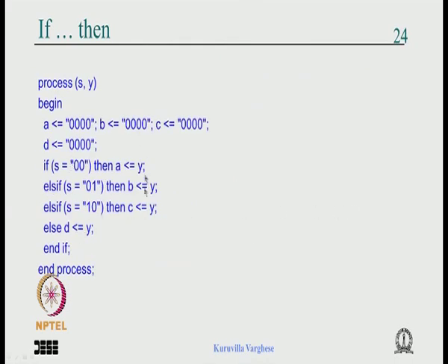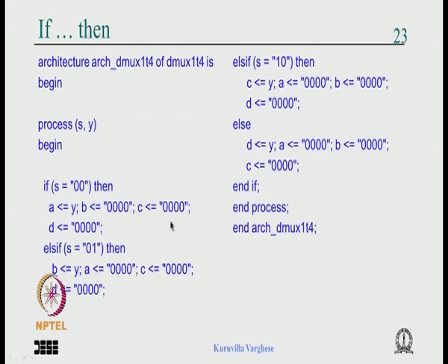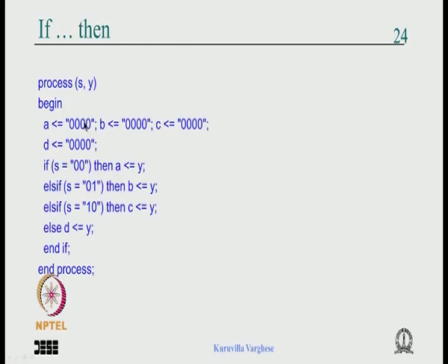Similarly, instead of repeating all the other signals here, you could initialize everything at the beginning and only write what is changing, like in the case. So these are different ways of coding. You can use if, but the case is better. You can use with select and when else, but definitely the case or if is better, and in that the case is better.